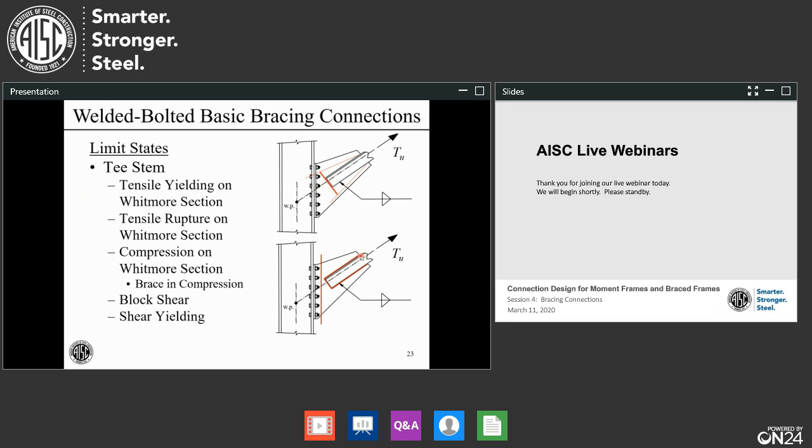We also have block shear, a pattern like this U-shaped pattern shown there. Have block shear of the stem. Seems like we could also have block shear along the L-shaped pattern that went down like so and over this way. So you just have to use your engineering judgment to define these patterns and check whichever ones you think are reasonable and believable.